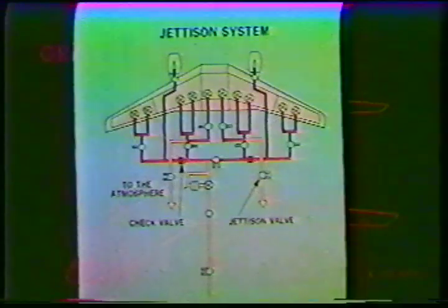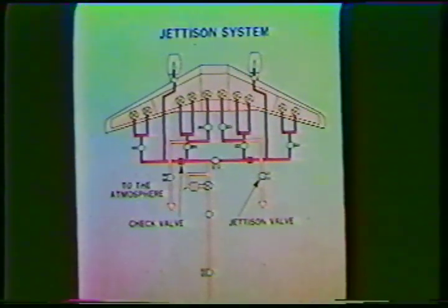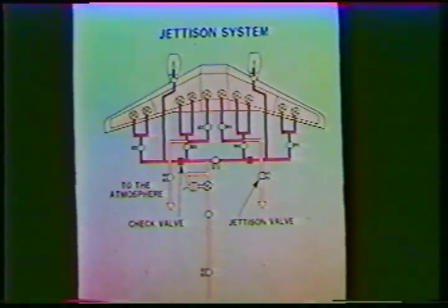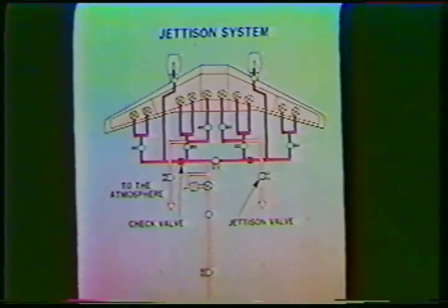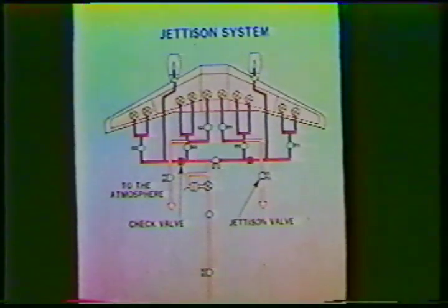A fuel jettison system is installed and designed to dump fuel from the inner and center fuel tanks only. Dumping fuel from the outer tanks is not possible due to check valves.